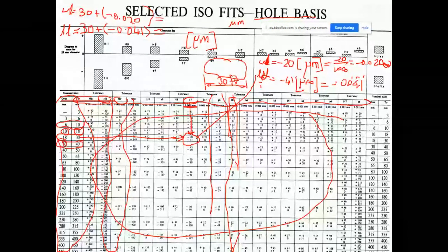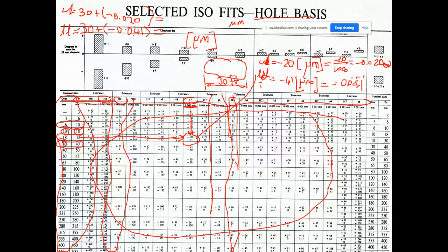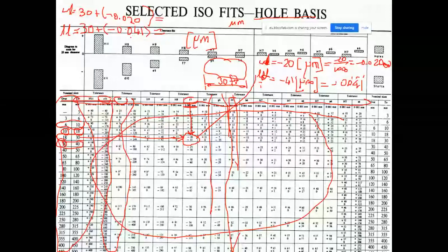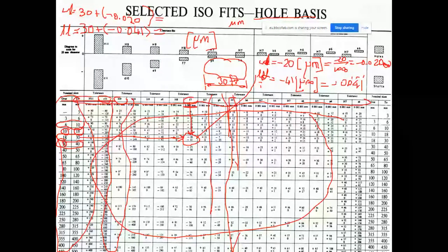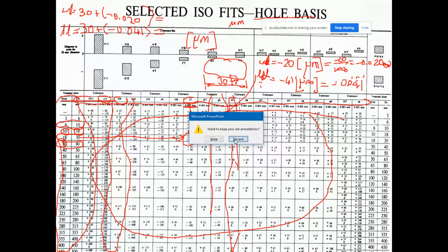Here, showing the dimension, the deviation value with such a figure, we highlight that the precision resolution in sizing this feature is in the order of tens, hundreds, thousands. In elementary school, the math teacher said, are you stupid? Why are you writing the zero? In engineering, it is extremely important to highlight the precision. It must be shown. Okay, if you want, I can use a pocket calculator.